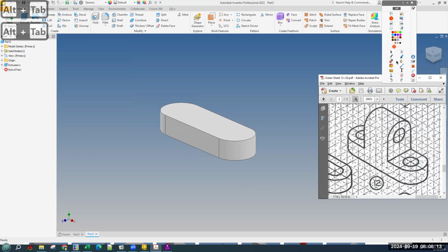I'm actually going to do these 2 holes first because they'll give us a nice, easy snap. The order doesn't really matter, but I will be doing these first. They're each 2-inch diameter circles. And we know they share the same center point as this arc because those construction lines go through it.